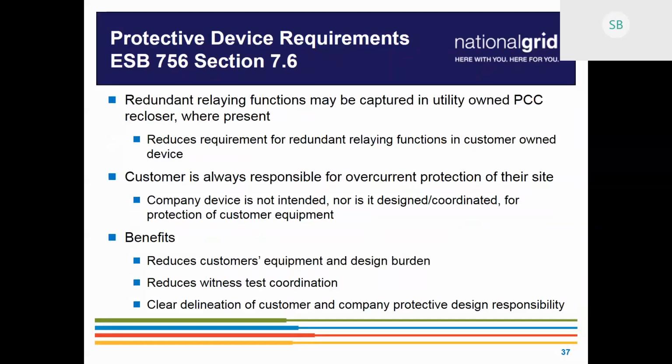So what we would do for a witness test there is just check to see that the fuse size you have on site complies with what you had in your design, just for a reasonable check of what the design was lining up with in the field. But the real redundant functionality would be in our recloser. Thank you.